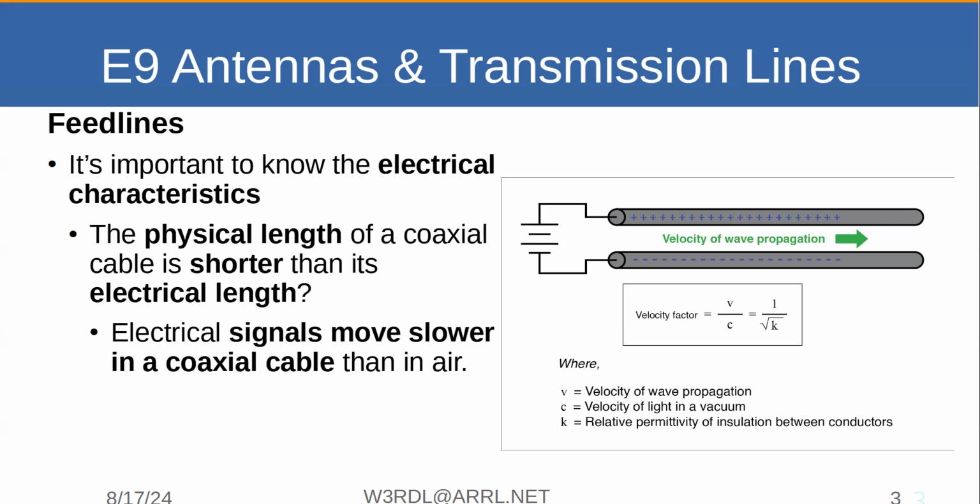And obviously they don't measure it with an infinitely long piece. So they calculate it based on the distributed inductance and capacitances. And there's formulas for doing that to figure out what the actual characteristic impedance will be.